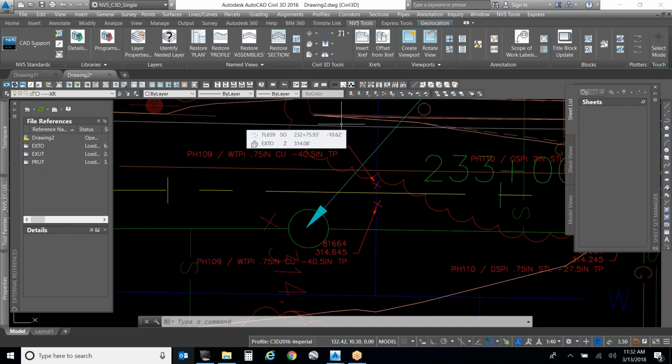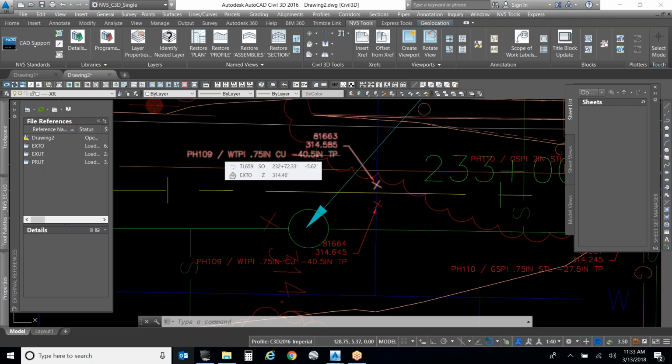So you suggest to actually delete the original pipe networks and add them if we have the pothole information? Yes. The issue with going method 1 and doing all the assumed elevations, the only way to then adjust that data down to the correct invert is to do a lot of math, right? You take your point surface, minus the cover, minus the thickness of the pipe, minus the diameter of your pipe. It seems like a lot of math where you're going to fat finger or mistype or miscalculate, right? In my opinion, it's a lot quicker and easier to delete your pipe and recreate it using the pipes from points. Does that mean we need new labels to do it?